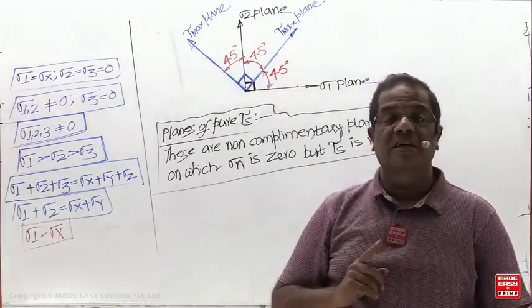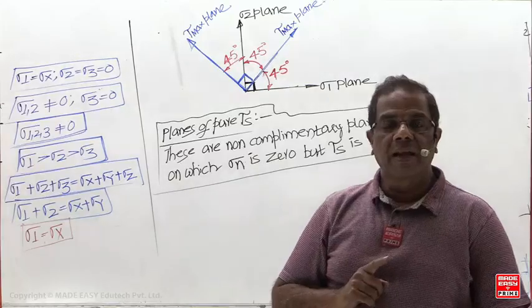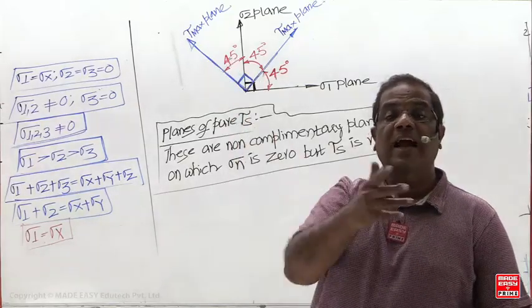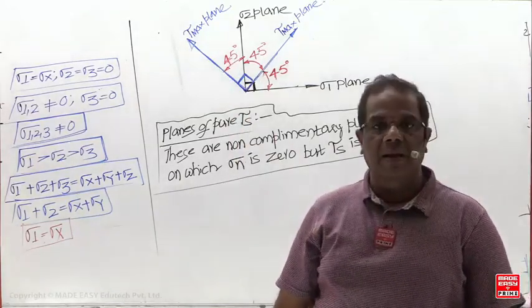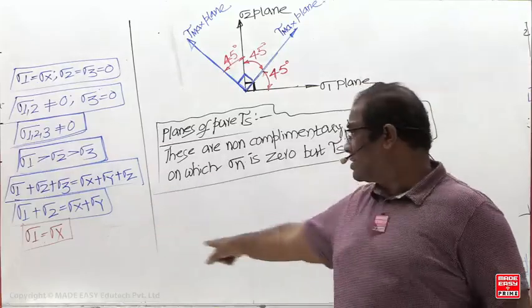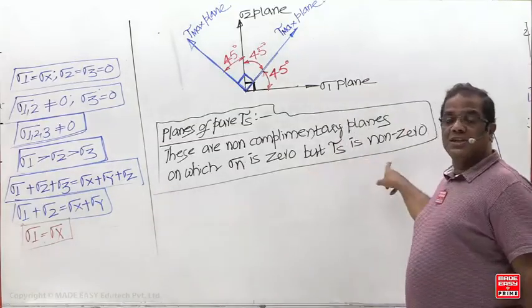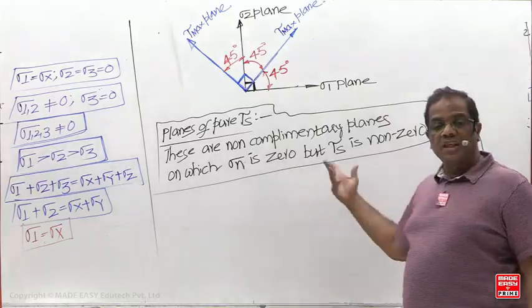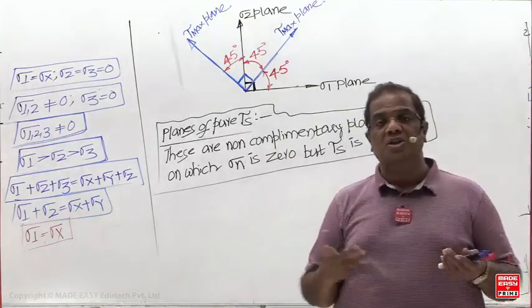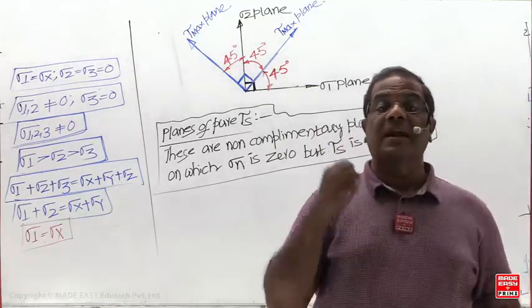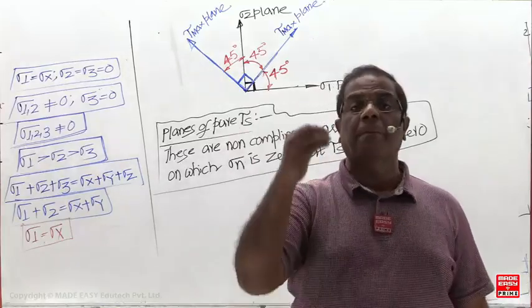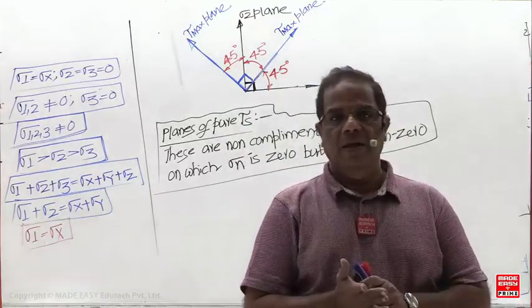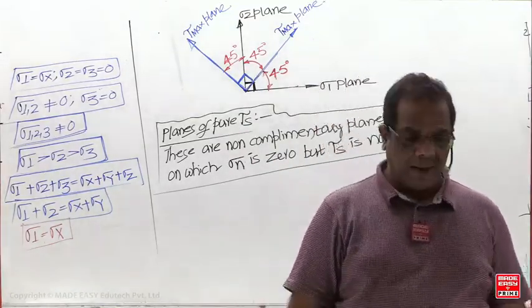On that one, shear stress is maximum, so we can locate the fracture plane for ductile material. But on this plane, normal stress is already 0 and shear stress is non-zero, so neither normal stress nor shear stress is maximum. So there is no practical significance; this is for academic purposes only.